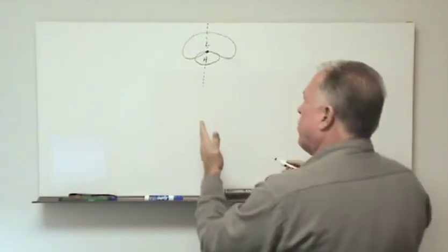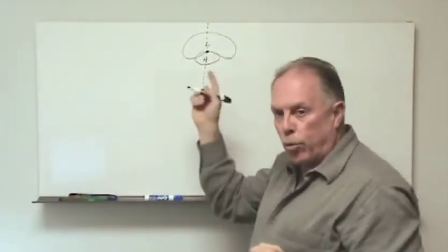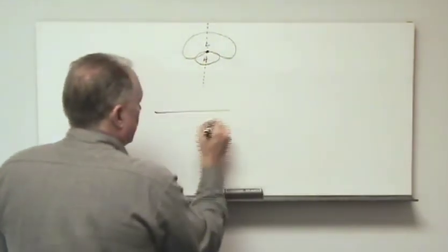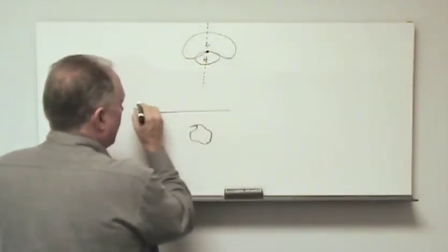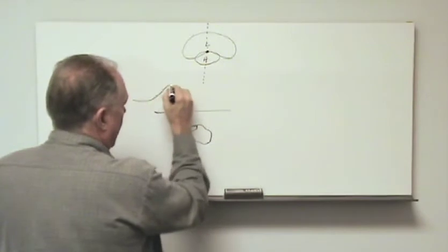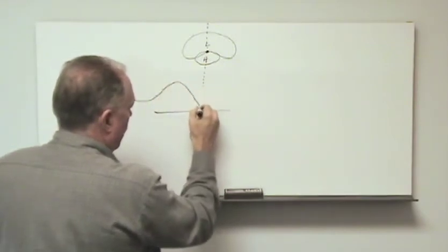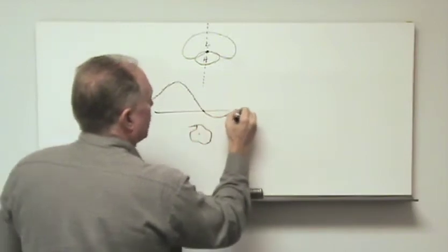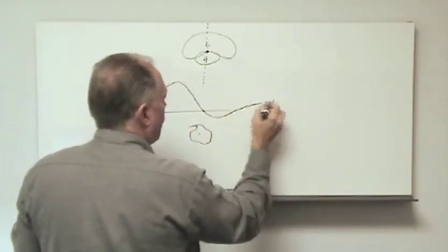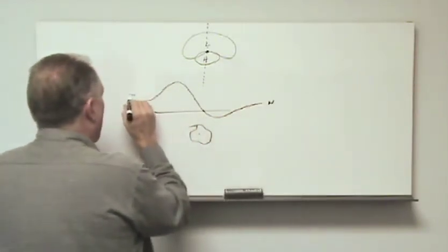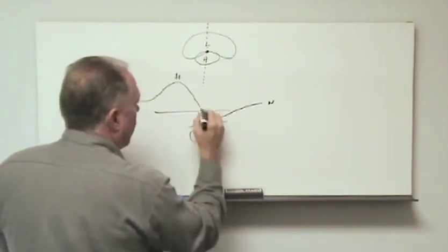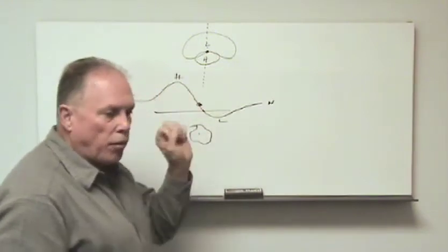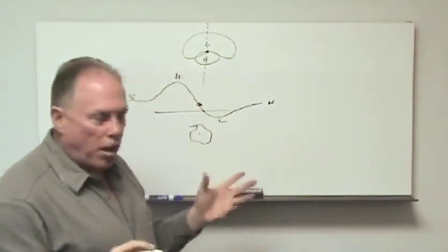If we were to extract a survey line through the anomaly, here's the anomaly, and we would see a high to the south. We would go through an inflection point where the object is, and then we would see a low to the north. I wanted to point out, however, that this is only for the northern hemisphere.